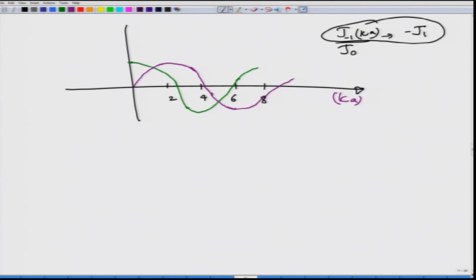Okay. So, this is for the LP mode with L equal to 0 and the LP mode with L equal to 1, and the corresponding solution sets. So, this is one region, right. Let me use a different color. This is one region where the solution is only coming from this one, and the solution here is the LP01 mode, 0 standing for L equal to 0. Once J0 goes through 0, then you will have the next set of solutions, and this next set of solutions will be valid until the next root of J1. Remember, kappa A has to switch between J(L minus 1) and J(L).